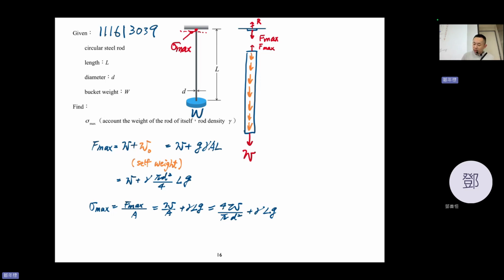When you stick back the two parts of the material, they become one, right? And then your internal force cannot be seen in these figures. Okay, so that's the basic concept. If you want to see the force or the stress, you just cut it, cut it, cut it. All right. So normally we will just cut one section to make everything easier.